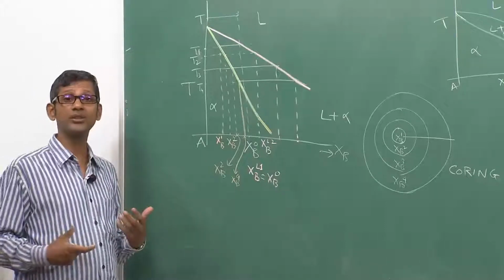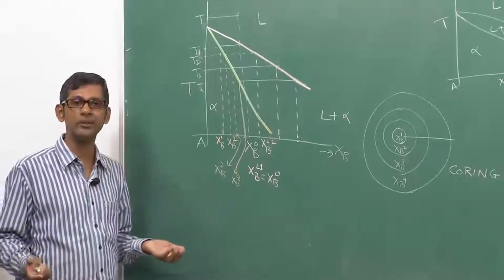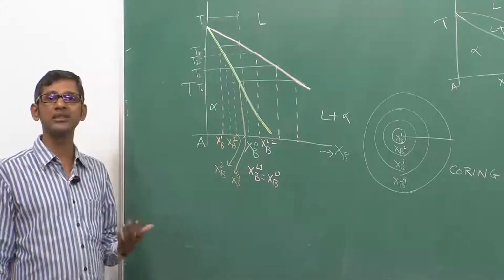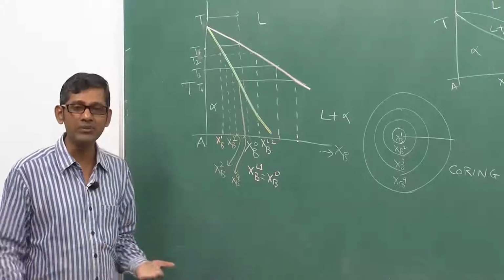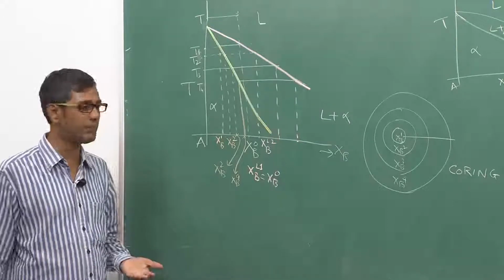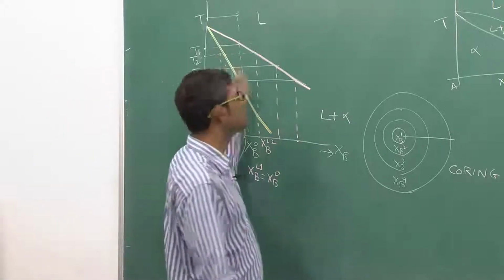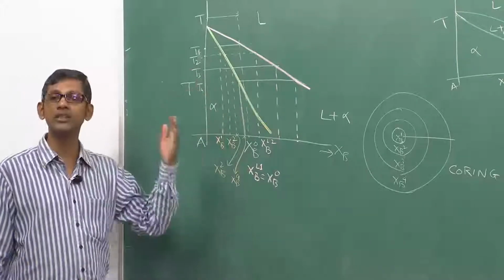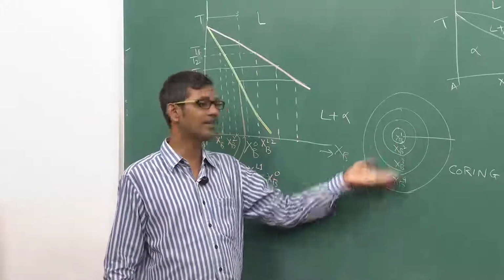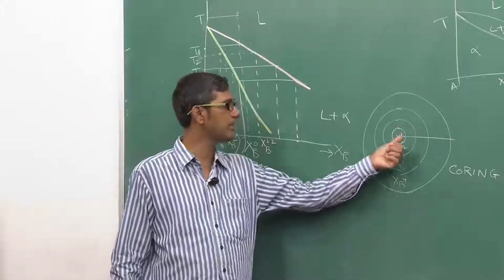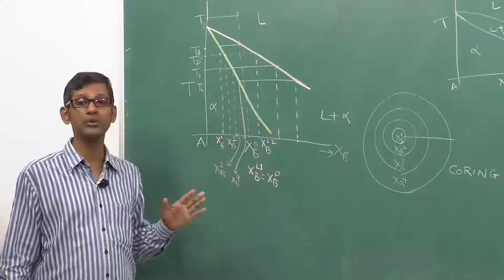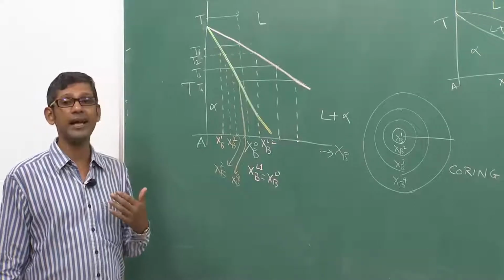But in the actual situation, normal solidification, we cannot do that. We cannot keep the system for a sufficiently long time, because in industry or even research laboratories, an experiment will have a time scale, and that time scale cannot be infinity, because there is production loss or many other things can happen. Because of that, the temperature is dropped from the liquid to the solid continuously, and because of this drop, this is very common. The situation where the compositional gradient develops from the center to the periphery is very common, and it has been observed in actual practice.